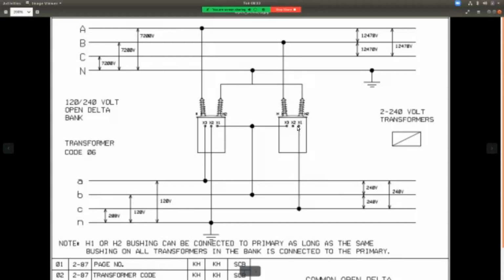All right. My C phase, which is on the next transformer, is what? 240. 208. 208, my bad. I can't see that. I understood. I know it's a little bit blurry. It's 208. Why is it 208? Because it's 1.732, isn't it? Exactly. Good catch right there.